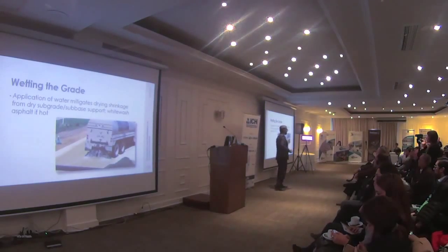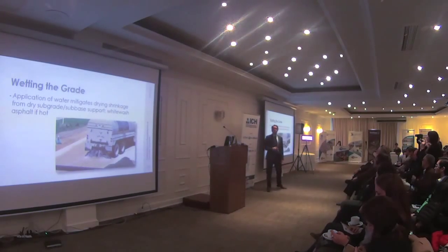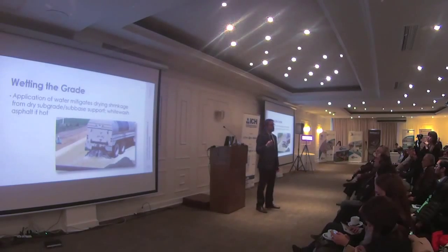If we're paving on top of an asphalt layer, like we would with a bonded overlay on asphalt, or otherwise, we might use some other means of cooling the surface, like whitewashing it with curing compound.